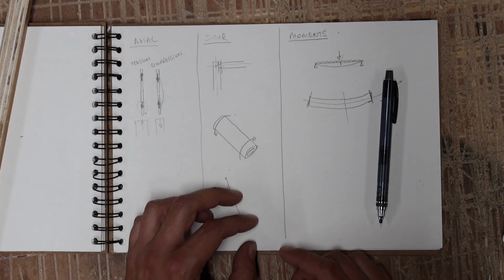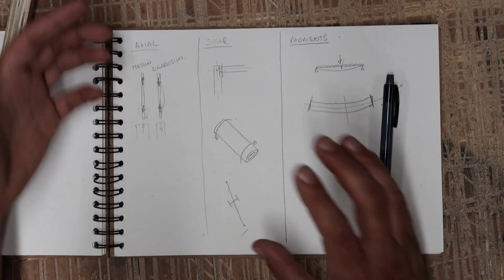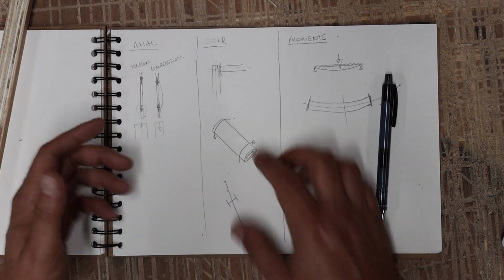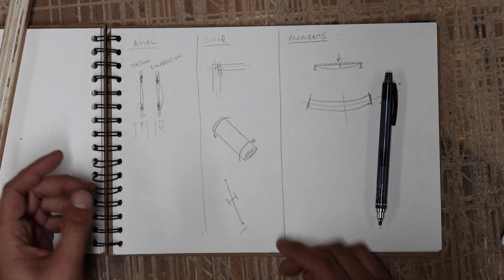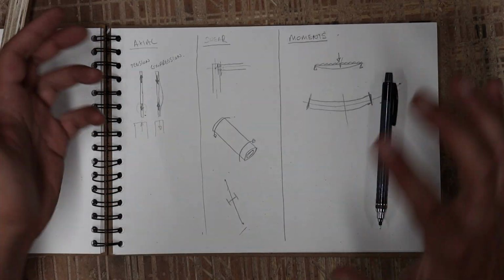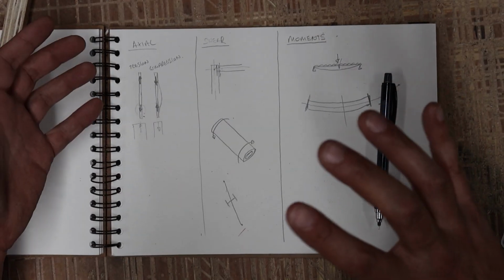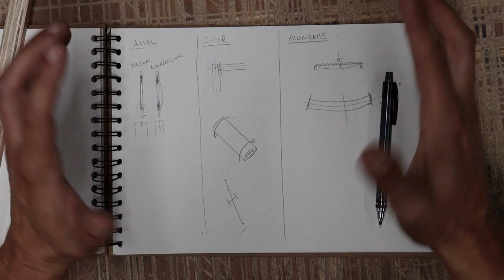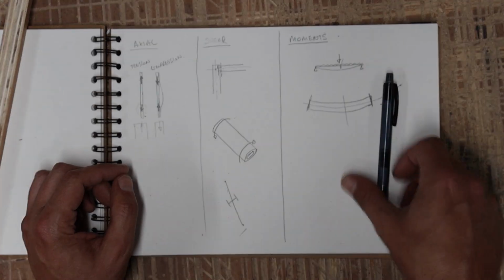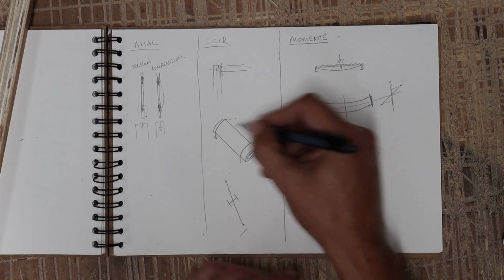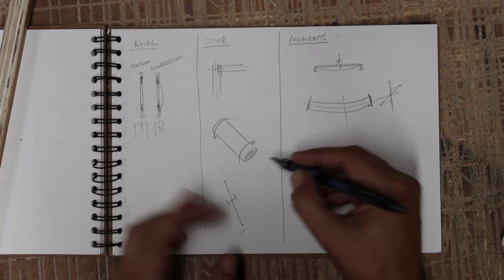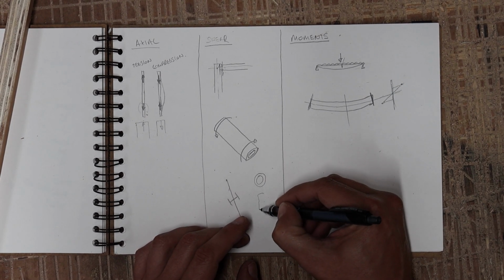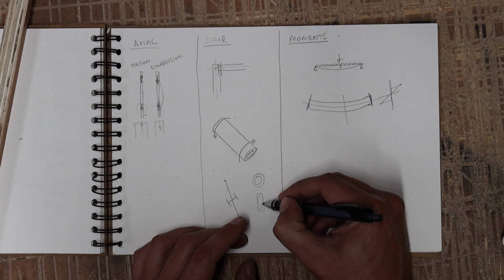Now with torsion, that's what this twisting is, this pure shear. This can cause quite big deflections because these steel beams, all materials, don't really like torsion. If you imagine that sort of action, that's quite a deformative action. It's very distressing to the material you're putting that force under. So the best shape for torsion is tubes, whether a hollow circle or a hollow square. That's what we generally tend to use for things that are in torsion.